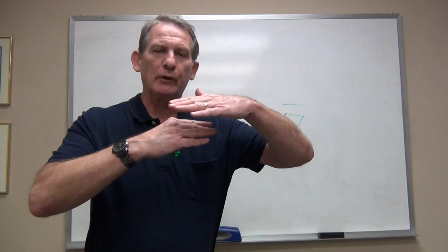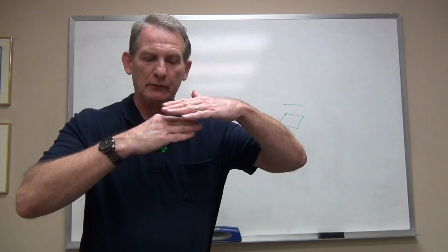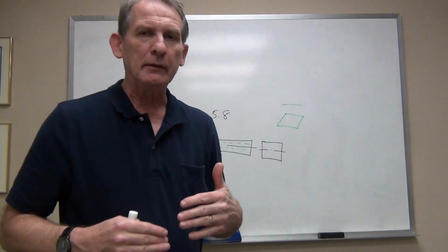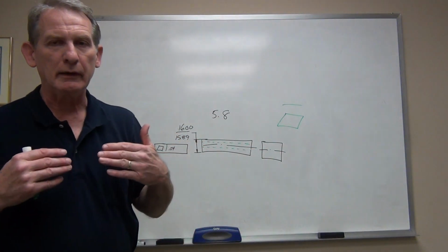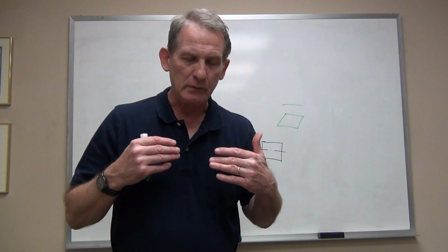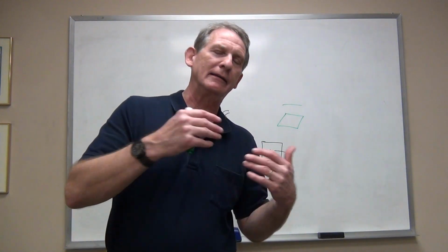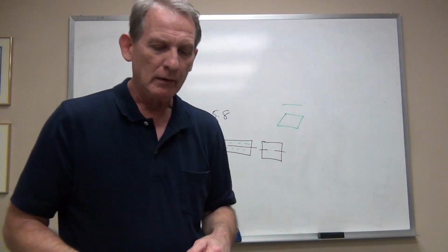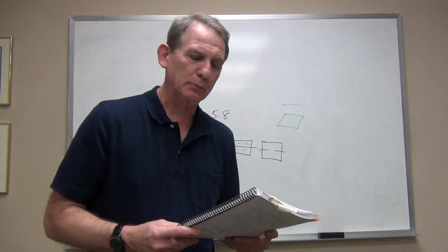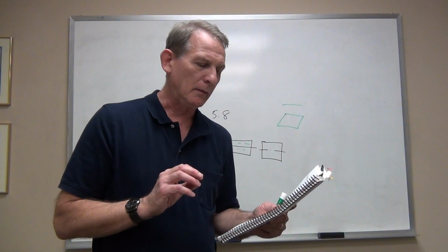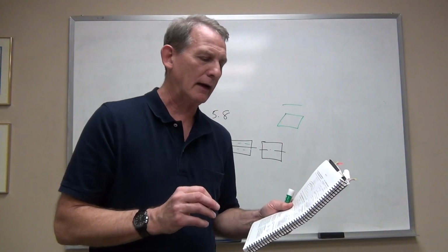In this case, they're 40 thousandths apart, so they're definitely a tighter tolerance. But they are about or established around the derived median plane, which is on the interior of that bar. Now, if you look at the explanation there, they kind of explain to you what that really means in effect.